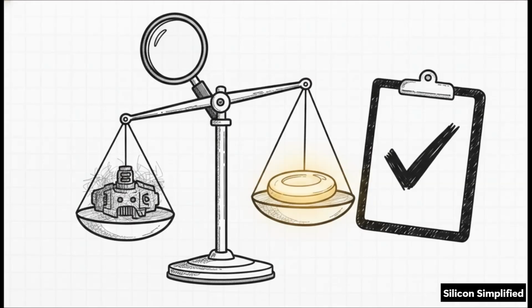This is exactly where your scoreboard shines. During the check phase, the scoreboard evaluates functional correctness by comparing the actual outputs from the DUT against a golden reference model. After that, the report phase prints out all your summaries, your passing metrics, and hopefully, absolutely 0 mismatches.